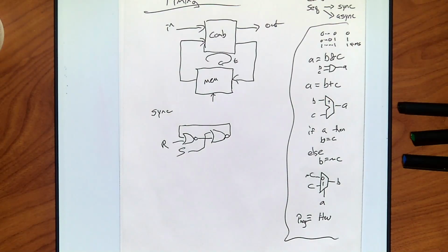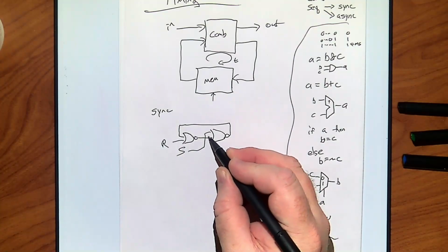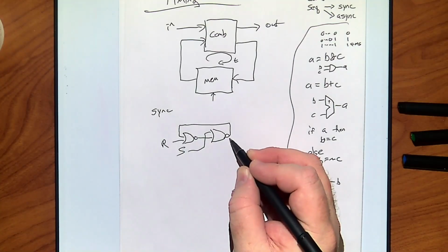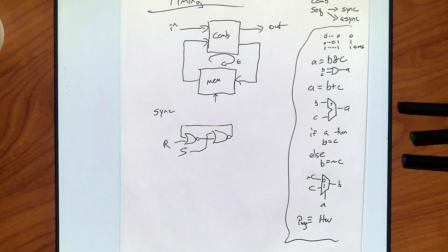The advantage to this is you can see that it takes two gates. My worst timing, right? My best timing, I go from one thing to an output, the other one two. So it can take up to two gates worth of logic to get there. On top of it, there's extra logic in front of this to actually turn it into a flip-flop and get edge timing. We could have two or even three interlinked flip-flops depending on the style of edge transition we're going for.